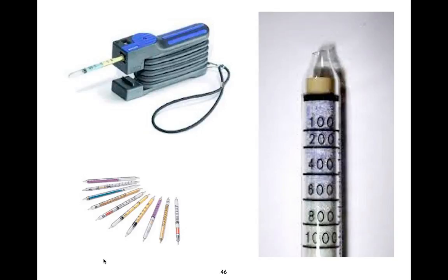Okay. Well, the air doesn't move around that much, lack of circulation. The real reason is human breathing. Thank you, Dave. Exactly. People are breathing into the air. People breathe in oxygen, they burn it, they exhale carbon dioxide. They're adding carbon dioxide. You could get carbon dioxide from combustion products, but that means something's wrong. That means your furnace is not venting properly. Something is very seriously wrong.